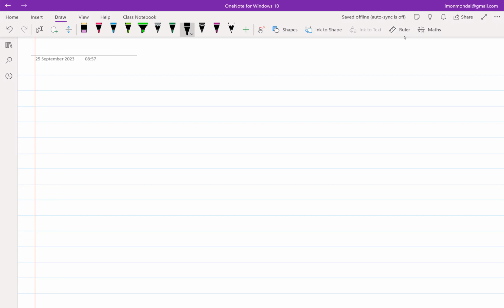So what is the problem with that? Let's take the example of a music system, right? You have your favorite music system. You want to listen to your music at a certain volume, so you turn the knob or slide the slider and set it at a certain volume. And if the ambient condition changes, like temperature changes, or you take the same setting to maybe Ladakh or to the Thar desert or something, where the temperature will fluctuate from +40 to -40, the gain will change, which means the output volume of your sound will change, right? So this is one example of where, if your gain is dependent on temperature, it can be a problem.